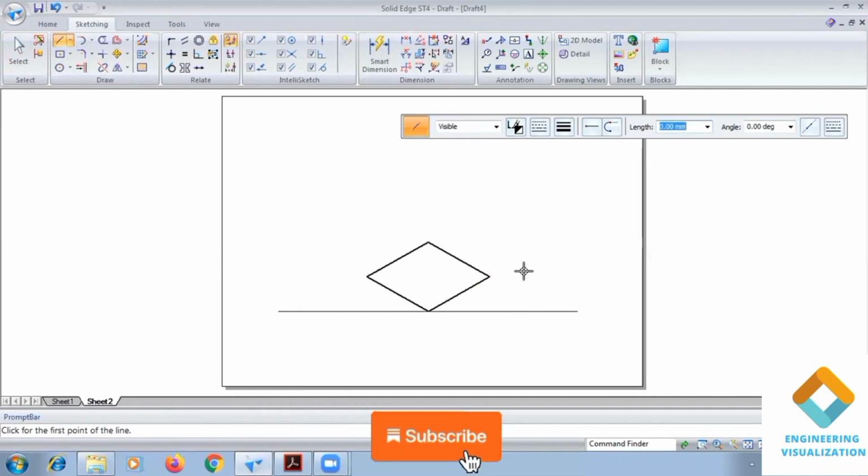Now for the vertical height, we need to give a height of 50 mm. One line I will draw of length 50 mm. Then go to the move command, create a copy of it, or you can directly do it like this. Length 50 mm, angle is 90 degrees. Now construct the top face. So the cube construction is done, guys. The cube we have constructed.